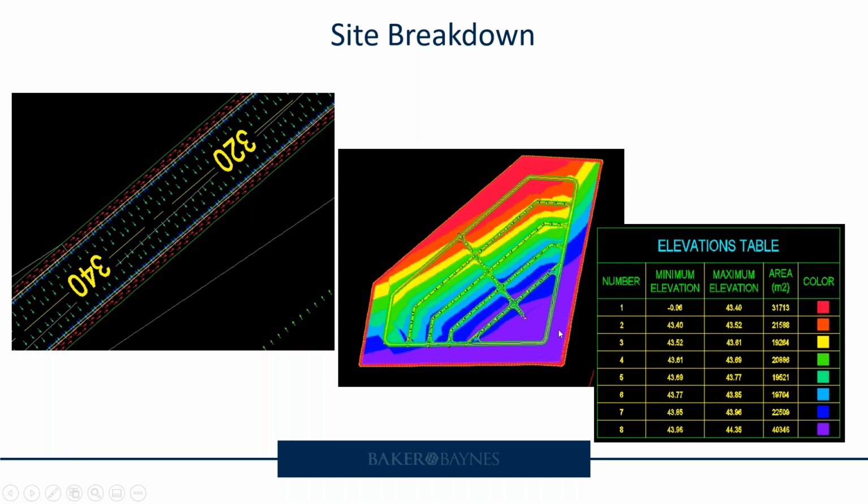So when I do my design for stormwater, I'm going to make it such that the outfall is going to be there, so it goes with the flow. Also, when you are doing your design, you would like to make the levels of the platform angle towards that, meaning make these portions a bit higher, which I have done. And then you would normally slope the road against the NGL, the natural ground surface, to form a channel, like a V basically. So the water flows in from the road as well as the contributing area, and it will be channeled quite nicely. That's what you can see here.